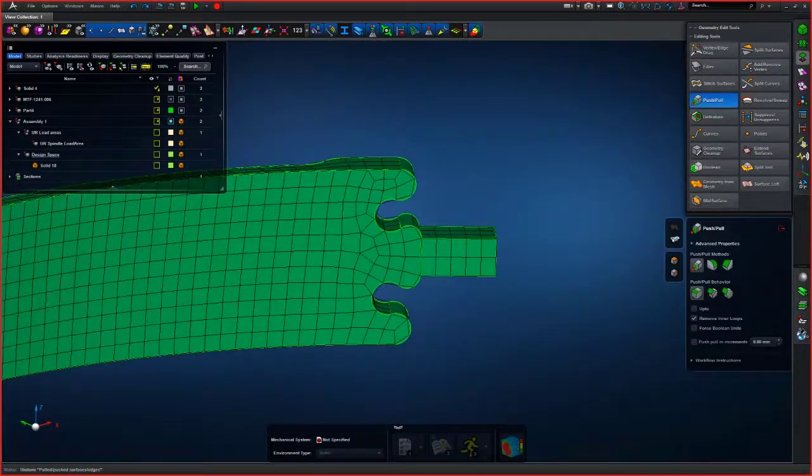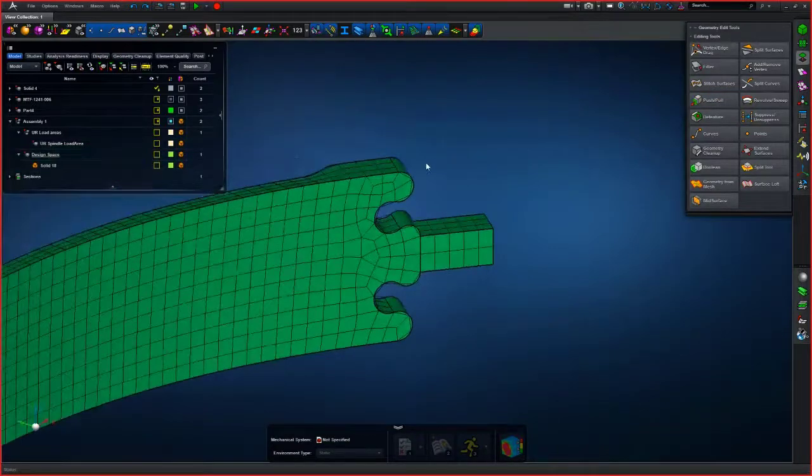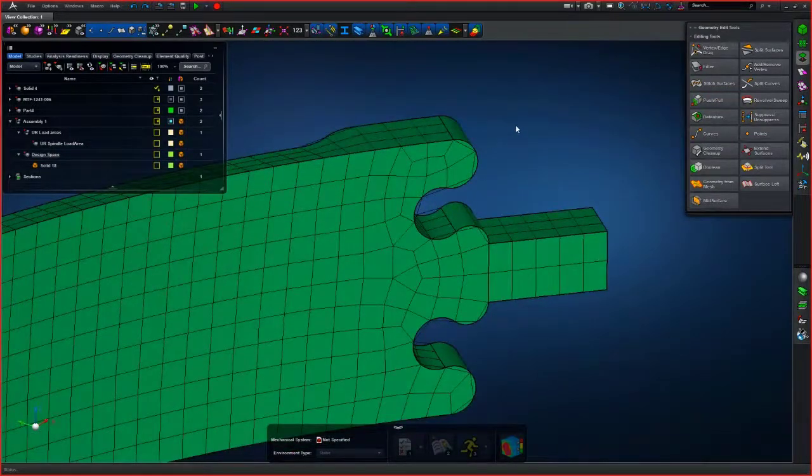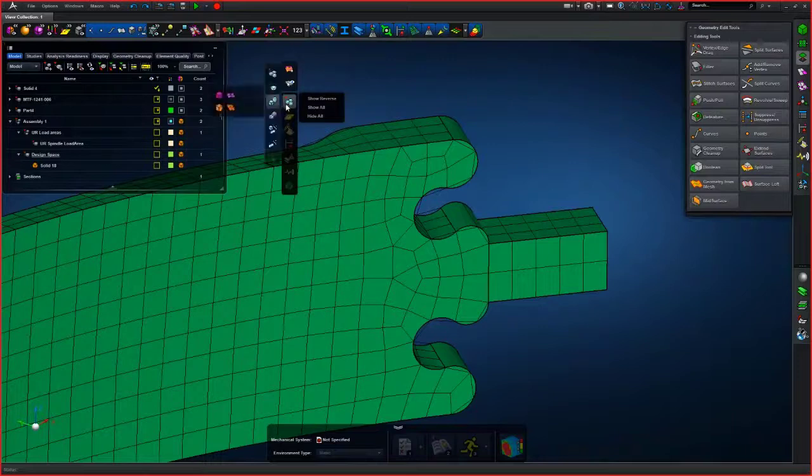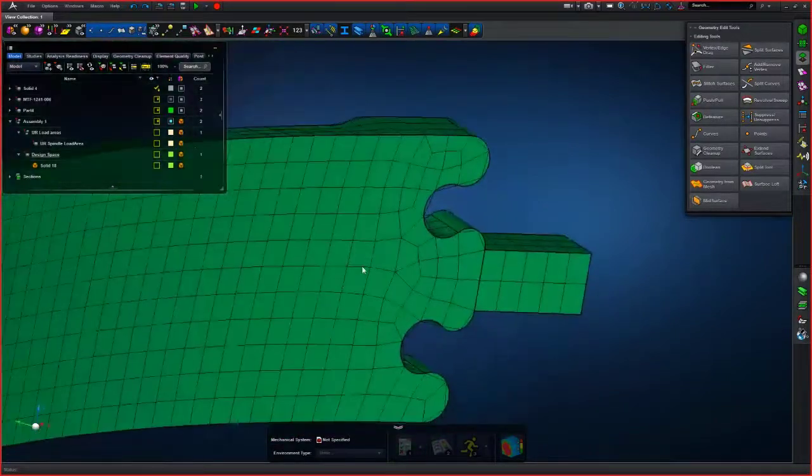There's one more question from Edwin. He says, thanks for the video, informative, useful features for CAD cleaning. Can you switch off the highlight model feature when you hover with the mouse over a body? That is a very good question, Edwin. And the answer is twofold. It's yes and no. There is no off switch button, but what you can do is to switch to an entity type on the filter that you are not interested in selecting or highlighting.